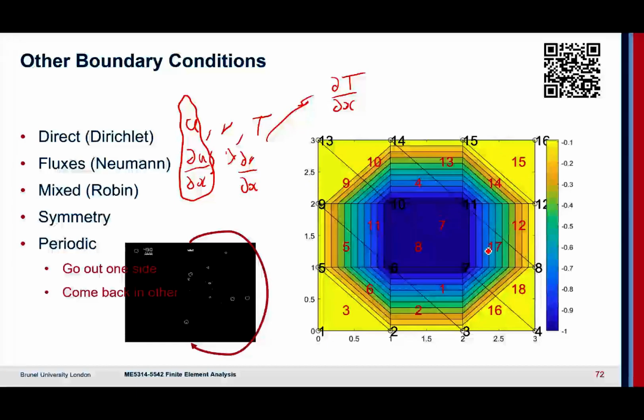Now, if you think about what this actually is, if we slice through here, you can think of this being the parabolic profile we've seen before. And you can think of this being like flow in a pipe. If you've got fixed walls and you apply a force, you'd imagine you get a kind of parabolic profile. Or if you've got a heated plate and you've got a fixed temperature at the wall, you get a kind of heat distribution.